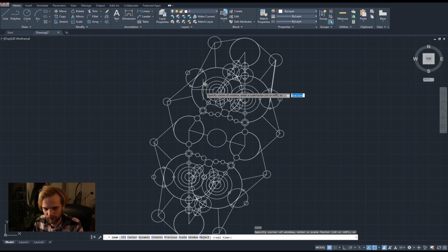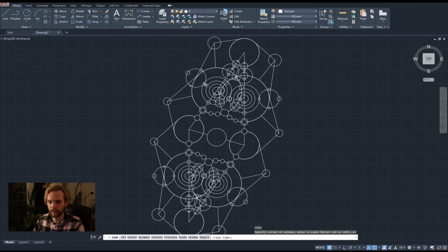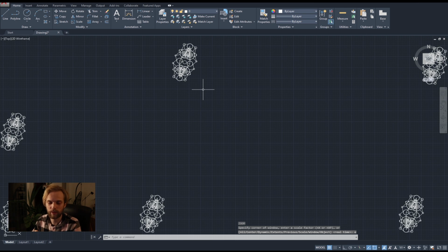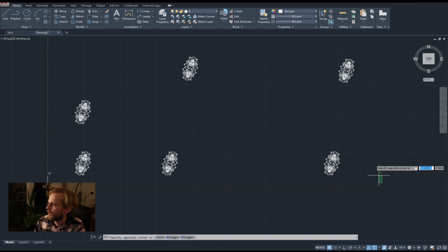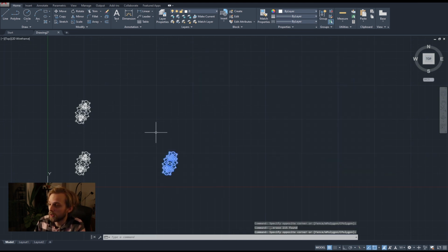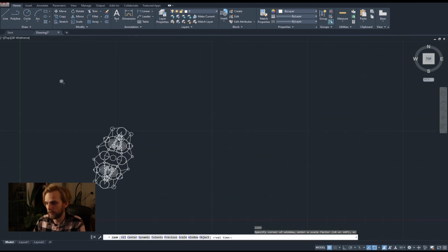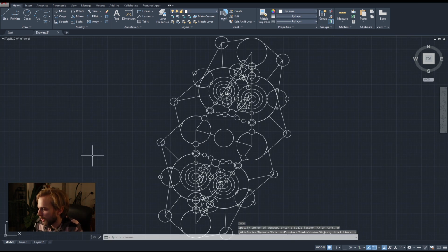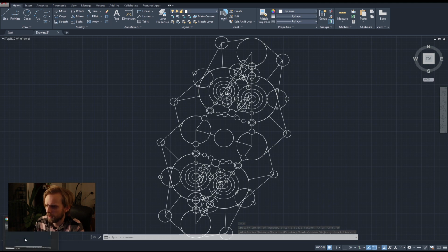I made a mistake during this tutorial. Zoom extents, you don't need to do Control A. You don't need to select all of the geometry. It already recognizes where the geometry is as if it's selected. So Z, enter, E, enter, extents, will zoom into all of the geometry in your model file automatically. You don't need to select all of them beforehand. That's useful. Yeah, forgot about that one. I apologize. Z, enter, E, enter. There we go. We're zoomed in. So that's that. Zoom extents, quite useful.